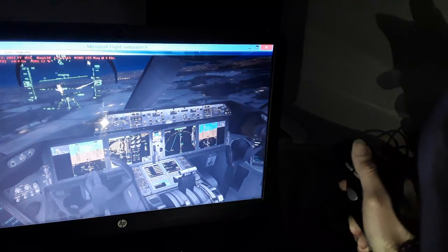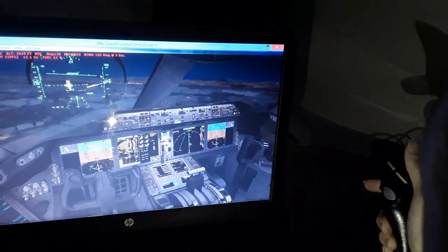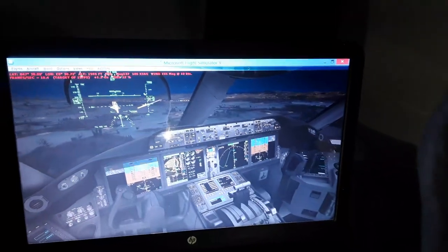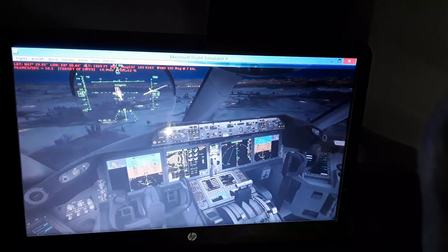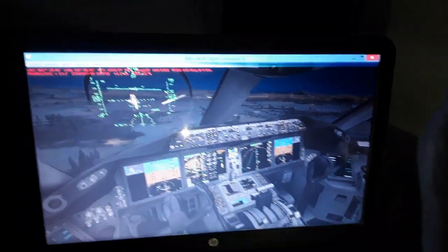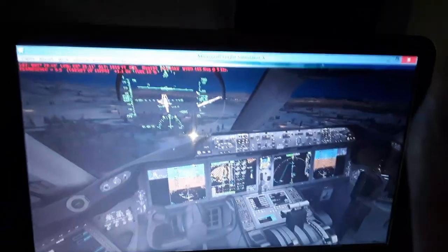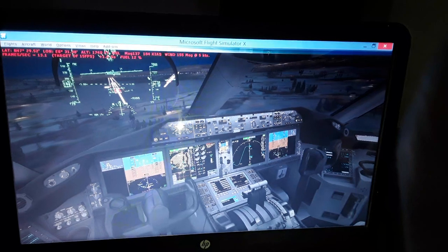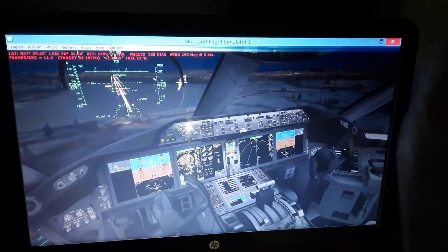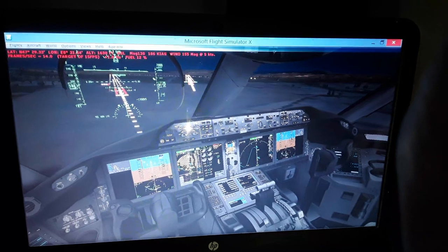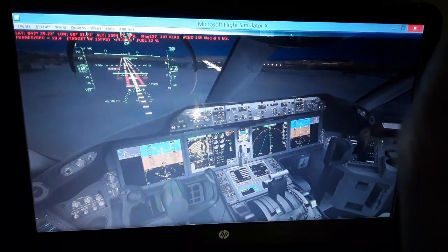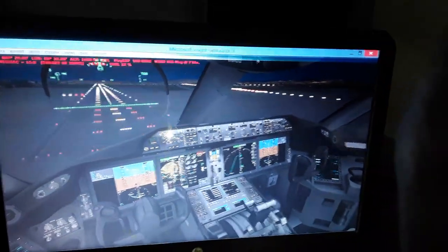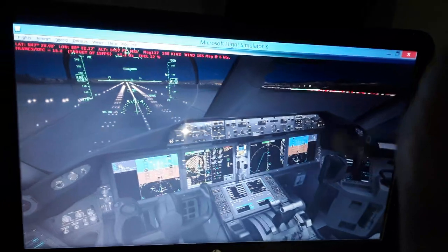A little bit right rudder now, a little bit left rudder now. We're gonna level off for the flare, as you're gonna see. We need red and white for the landing. Follow red and white, align with the horizontal tail, also used for leveling off for the flare. So we have red to white. We need to use idle thrust now. A level off for the flare.